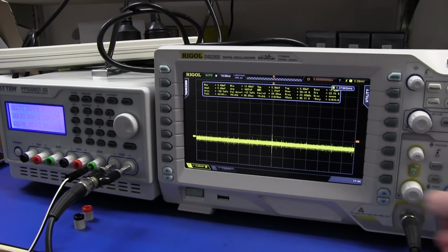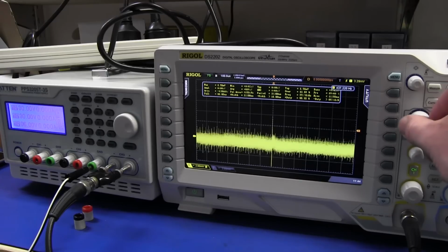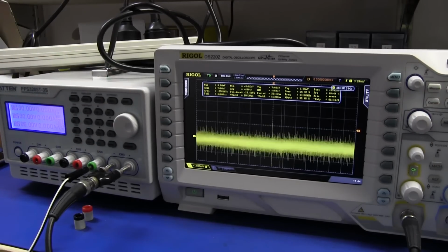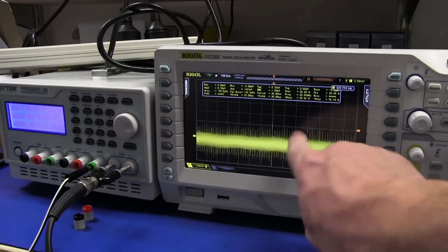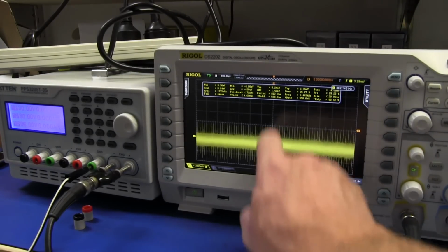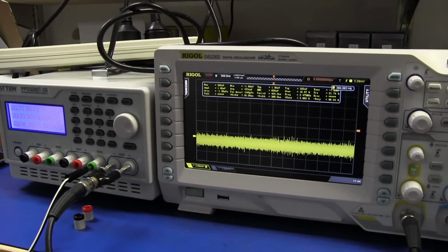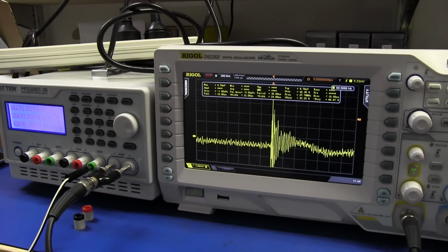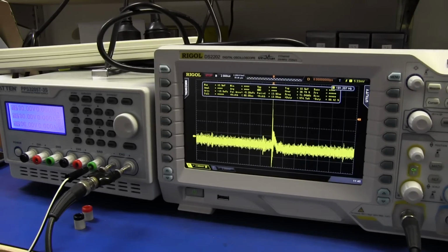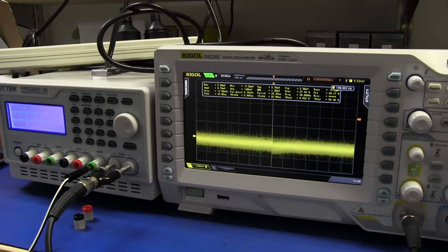So now we're talking. We've started to eliminate all of our problems here and getting towards more of the real noise performance of this power supply. So really, we still have, that's me, by the way, be careful, there you go. So we're getting very, very close. There's still a burst in there that's triggering off that. So obviously, we can move our trigger around, and there we go. We can single shot capture off that. So there is another burst event coming in there, but really, folks, now we can at least get a more decent measurement of our power supply.